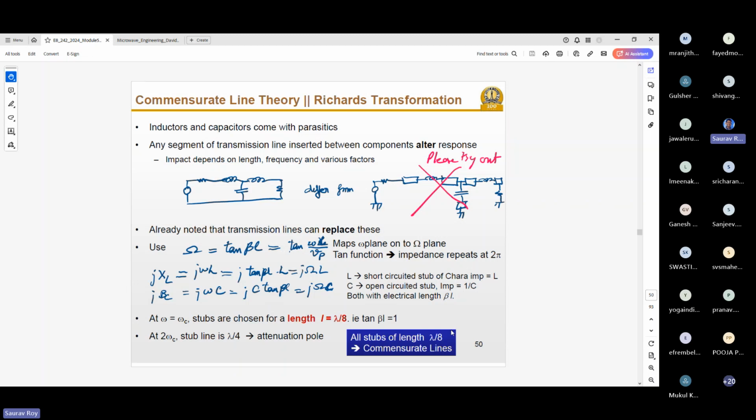No, it will not hold, or it will only hold where metal already exists. So that's why the pad is very vital for microstrip line design. For any lumped component you have to put, every time you have to use a pad there, unless there is already a microstrip line existing in your circuit just next to your lumped element. In that case you are safe. Otherwise, you have to put an extra pad.